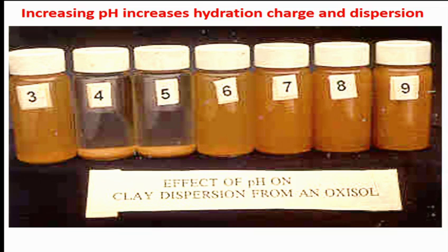When you go to pH 3, it attains positive charge, whereas between 6 and 8, 9, the soil charges are completely negative. Positive charge also can cause dispersion, and the effect is not because of cations like sodium, magnesium or potassium. It is because of chloride, sulfate, and so on.